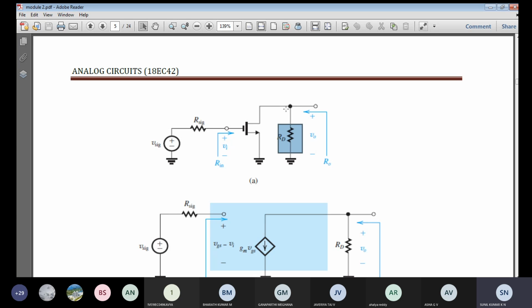In the next chapters, we are going to see that when we talk about the feedback or negative feedback chapter, we are going to have some resistance connected there. But in this discrete circuit common source amplifier, there is no effect between output and input. So there is no loading effect which can be seen from input to output or output to input. Hence, this type of amplifier is called a unilateral amplifier.